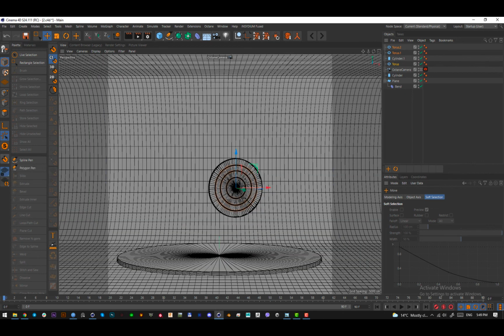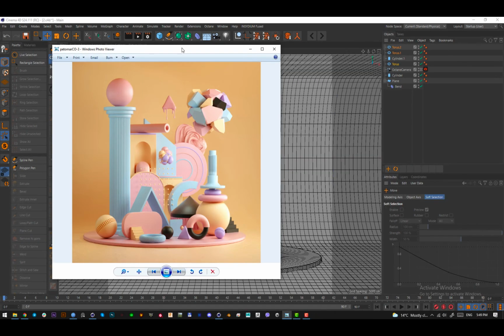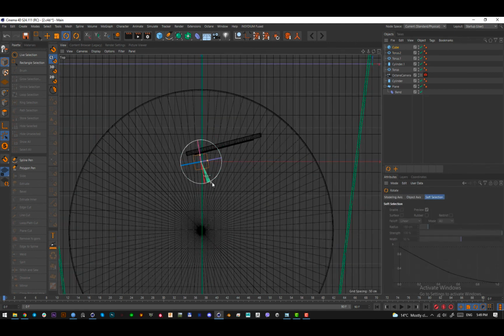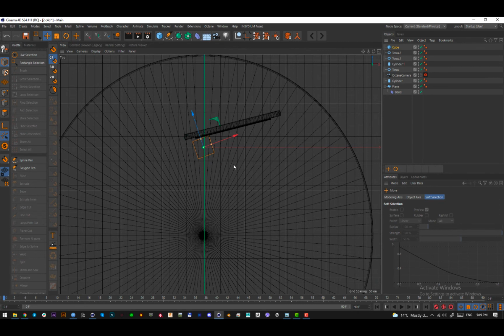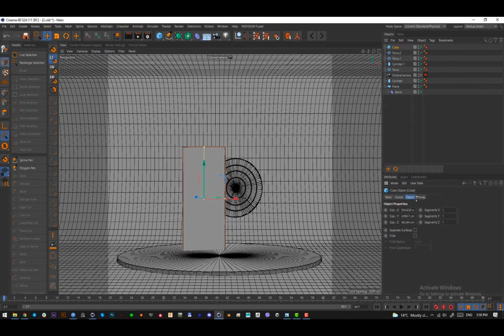Let's continue adding this one. So this one is very simple. It's a cube. Put a cube here, jump into the top view, rotate it like this a bit. Okay, using E, I am activating the move tool, something like this. Okay, rotate it here. F1 to jump into this view, increase its size like this. Okay, now click on the tube, go into the object, fillet, press this, and this is fine.